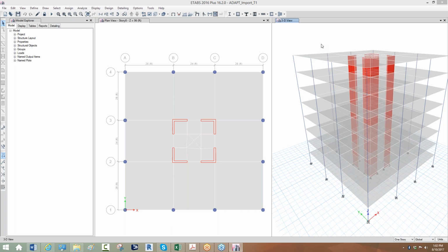If you were to import a load, for example, a response spectrum type of set of results or reactions from Etabs, those can be transferred into Builder, but inside of Builder, if we try to reapply them at a single level, the loads are not in equilibrium, so you're likely to run into an error because of that.